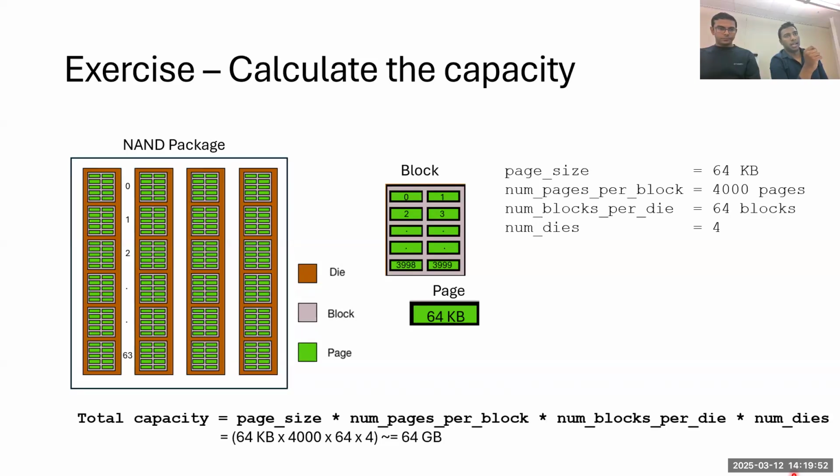Another thing is, in NAND flash, now we have 3D stacking. Because of the 3D stacking, we don't have to reduce the cell sidewise. We can just add more layers. If you do a Google search, I can't say the numbers that our company does, but you will figure out that Samsung or Solidigm announce that they have this many layers.